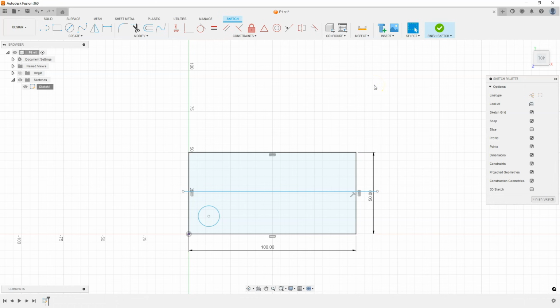And this line will be a construction geometry, that is auxiliary geometry that will not take part in the operations of creating a 3D solid based on a 2D sketch, but will be auxiliary geometry in a 2D sketch, and we can define dimensions and constraints relative to such auxiliary geometry, or we can use such geometry as an axis for the mirror feature. And to make this geometry just auxiliary geometry, select the geometry and select construction as line type.